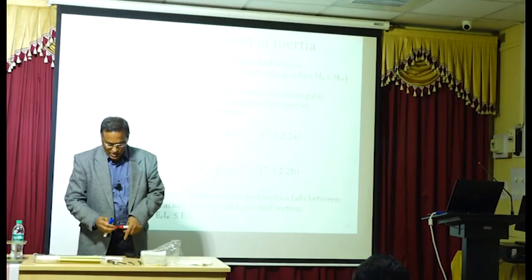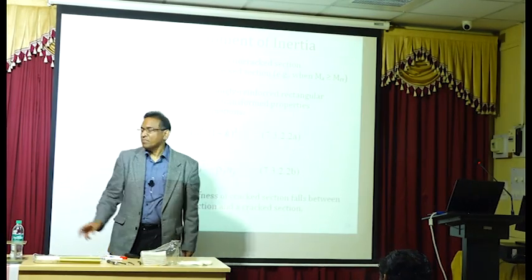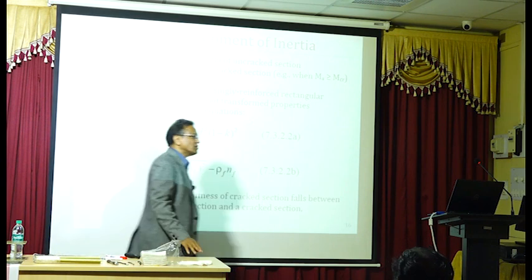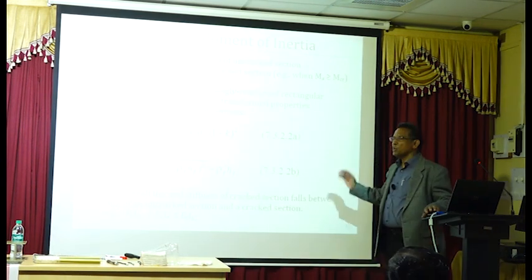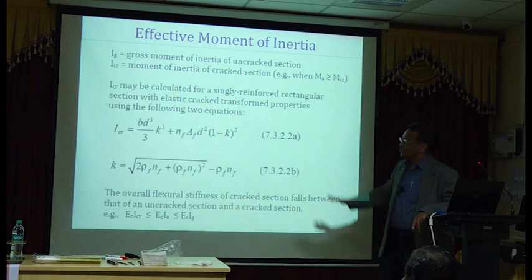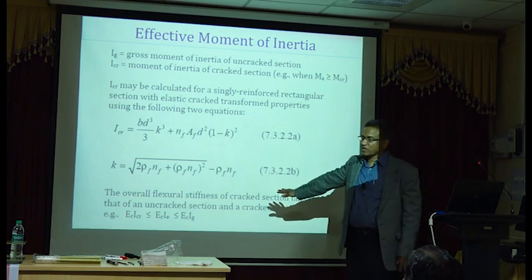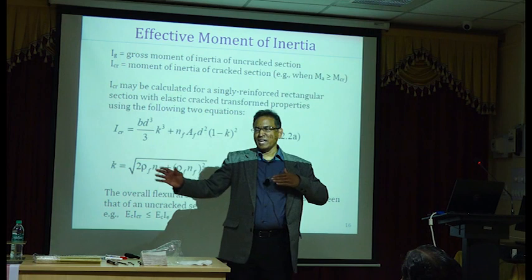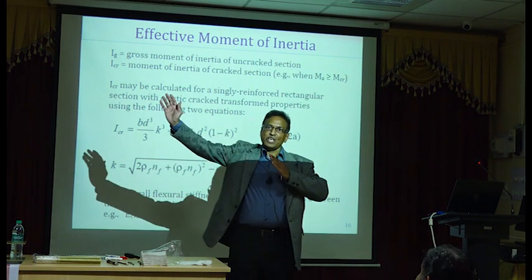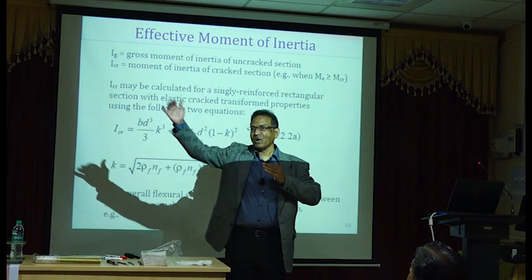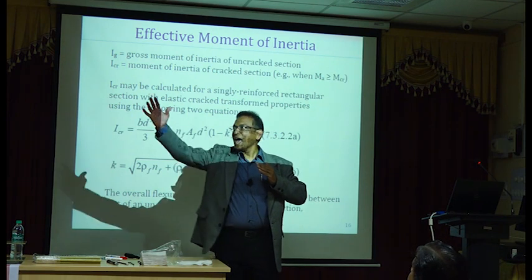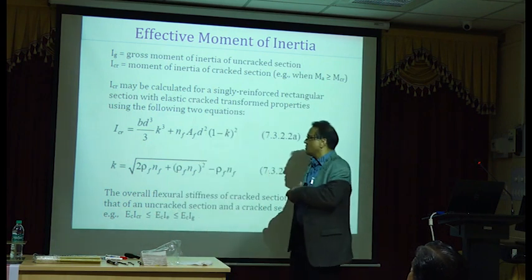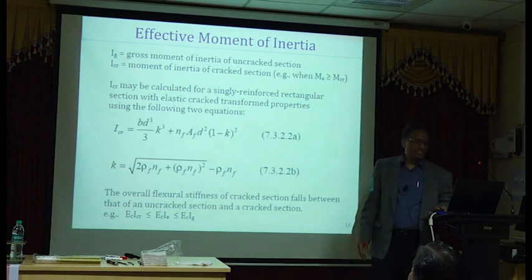All right, so there is a minor difference. You will see there is a difference between this and this when you plug in the numbers. But we will use ACI equations in all of this, because whenever you are designing anything, from start to end, use the same standard. Use entirely Indian standard or entirely ACI standard. Don't use half of this and half of this. That will become very inconsistent. So mixed mode is not necessarily good.